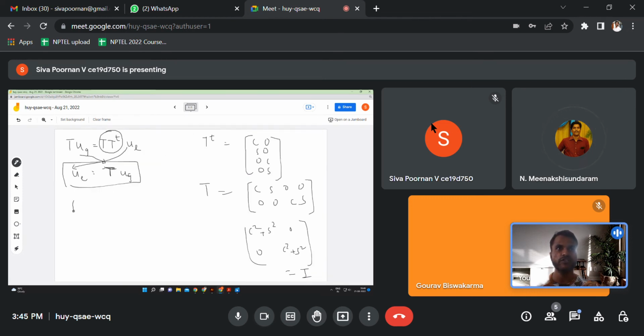So we know these local forces f1 dash and f2 dash are related through what we just found in the previous slides: EA by L times the matrix 1 minus 1, minus 1 1, times u1 dash and u2 dash, which are nothing but local coordinates, right?